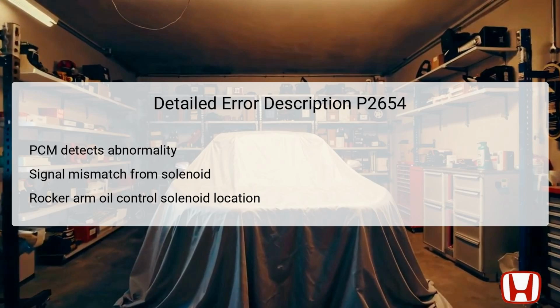Located on the top of the engine, typically near the cylinder head, this solenoid integrates with the rocker arm oil control valve. Under normal circumstances, the PCM sends an off signal to the solenoid, and any deviation, such as receiving an on signal in return, indicates a fault. This mismatch is crucial because it implies that there might be an electrical issue or mechanical failure within the solenoid or its associated circuitry, prompting the PCM to register the DTC.